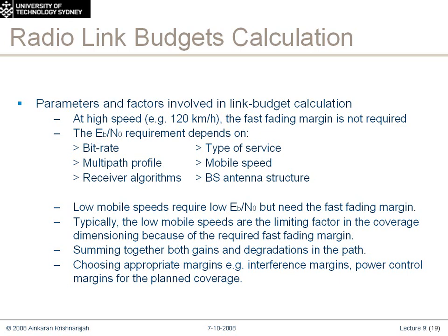So the next aspect here is the Eb/No, or the energy per bit over the noise, commonly known as Eb/No for short. So when I talked about the power of the base station relating directly to coverage, that was one dimension, and the second part was the capacity, right? And I said that each service required a certain amount of power in order to run. That service specification, or the power for that service, is specified by this Eb/No value. So for a voice service, you might have a low Eb/No value. For a 64 kilobit per second, the Eb/No value will be 3 or 4 times higher. And for a 384 kilobits per second, it will be again 3 or 4 or even 5 times higher. That generally translates directly into watts, the amount of watts that are required in order to run the service. So that's what that component is.